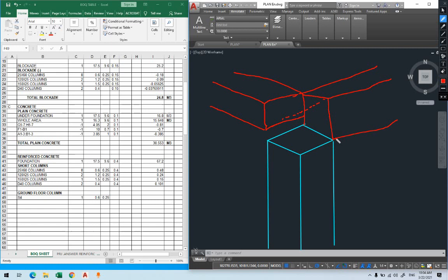So the column is supposed to stop at the bottom of the beam, yes? So which beam? The longer, deeper beam. For example, if this is 70 and this is 50, then when we're calculating the height of the column, we calculate till here, the 70, not here. At the end, sure, those beams are going to come. This is going to continue when we're doing the beams. Sure, we will fill this gap.